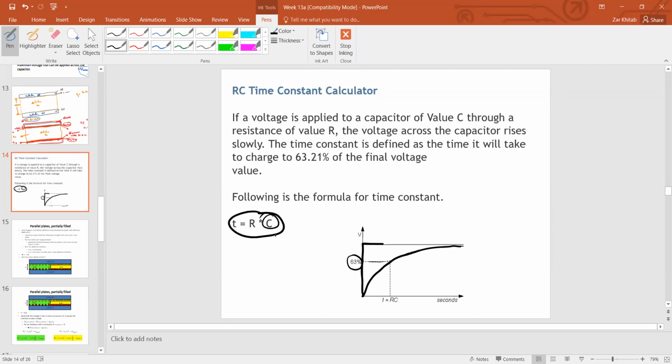And that depends on capacitance. So if the capacitance value changes over time, say in 4 years or 5 years, its rise time will change and your circuit will not perform in that way, especially if it's controlling some clocks. If it's taking some decision on the clocks, now your clock's duration will be disturbed because of the change in the capacitance, because of the change in the rise time, right? So these kinds of things will affect your system and your system will not perform like it was doing on day one.